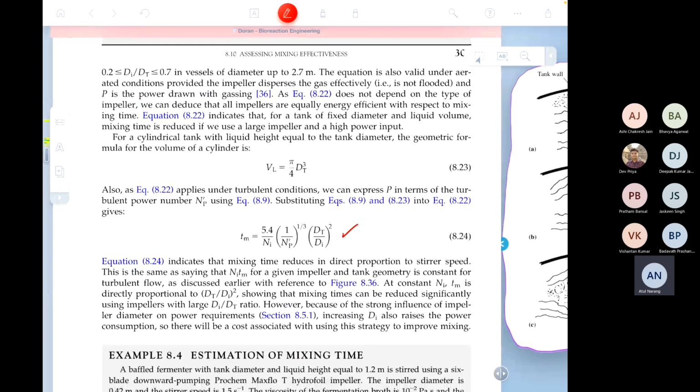The fundamental problem, as I pointed out, was that when you go to the 10,000 liter scale, it becomes really hard to maintain the conditions that you got quite easily in the 1 liter reactor. The reason for that, as we will see shortly, is that it's extremely difficult to get good mixing in a large tank, because the power that is required to get good mixing is so high that there is nothing out there that can give you that kind of power. So here's a quick calculation.